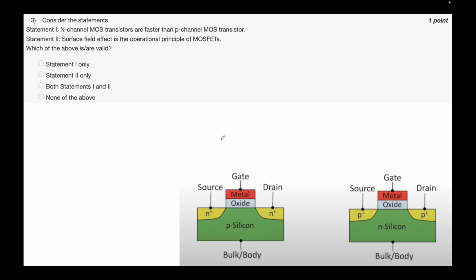So if you recall, when I'm talking about the p-type silicon, it will have an inversion layer of electrons. This is an NMOSFET. So I'll write mu n C ox W by L, again in saturation. Okay, it comes out something like this. Also for this, it will be mu p C ox W by L, times Vg minus Vt.